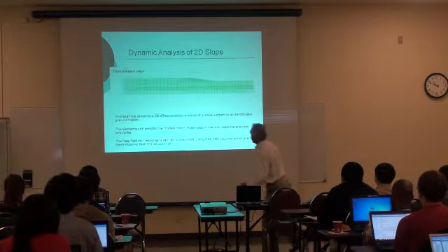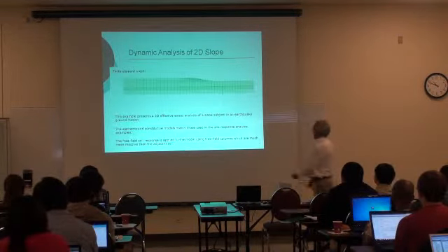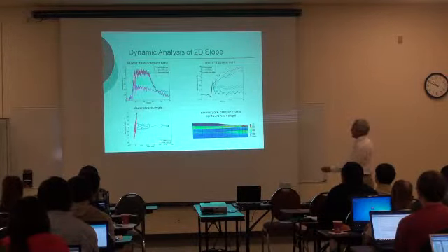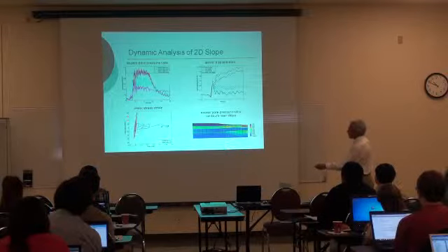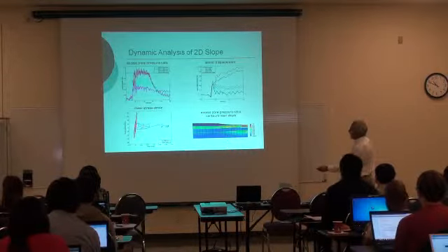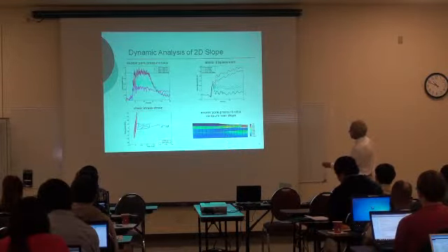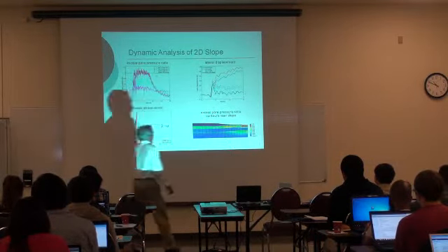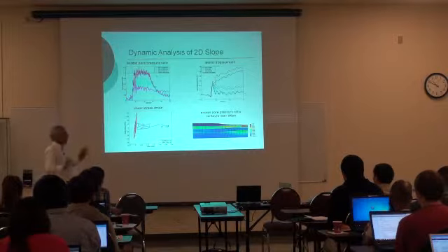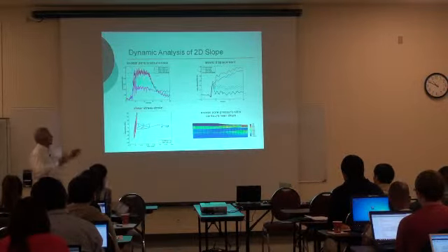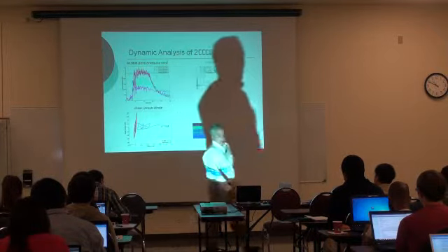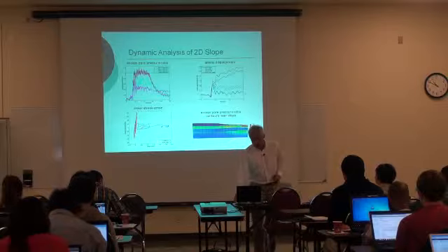So here what we did is to impose an excitation down here at the bottom. And of course, you can start looking at pore water pressures in the liquefiable layer. And look, this is the stress-strain response up here. And this is the stress-strain response at some point in the liquefiable layer. So you see that now you need to capture the two-dimensionality of the event, and in different locations it's going to be very, very different. That's why you have to go two-dimensional or three-dimensional, and then OpenSees can be used for that.